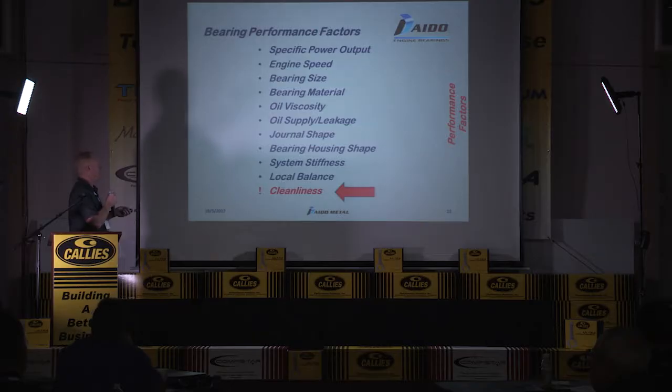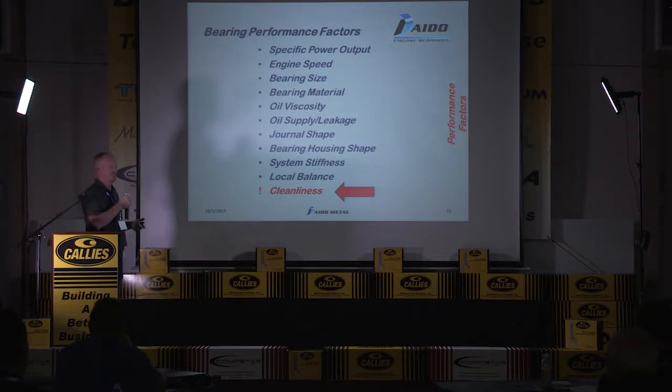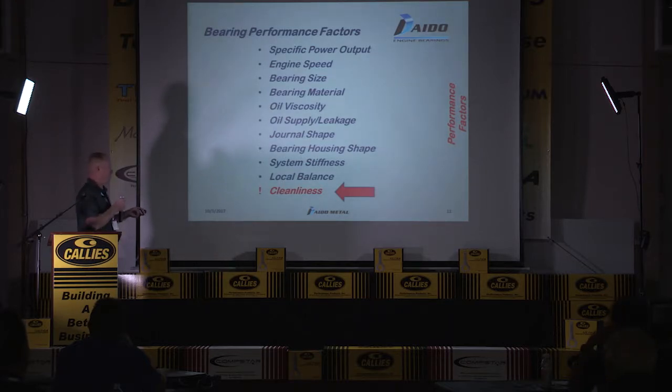And this is where we get to the performance factors, such as specific power output, the engine speed, bearing size, bearing material, oil viscosity, oil supply, journal shape, bearing housing shape, the entire stiffness of the system, including the stiffness of the connecting rods, stiffness of the crankshaft, stiffness of the block, and then your local balances.